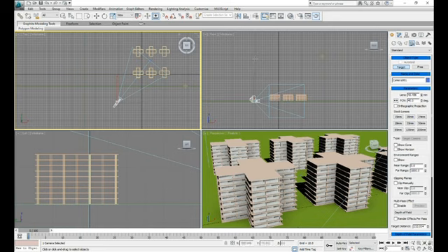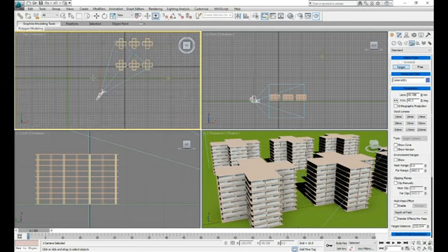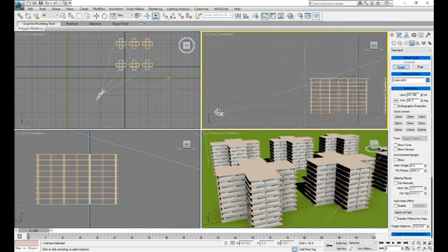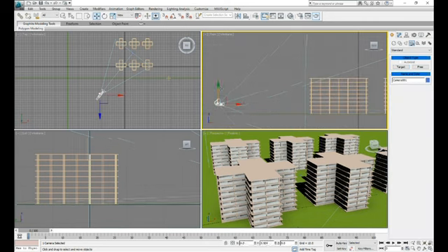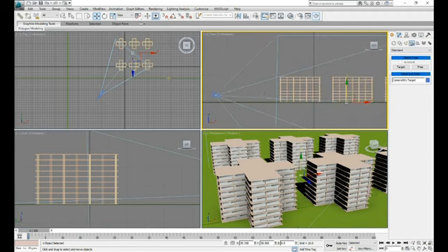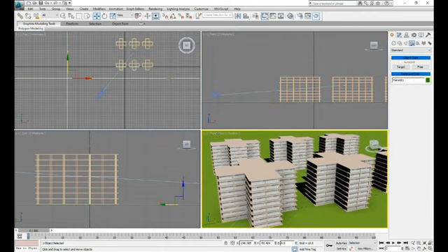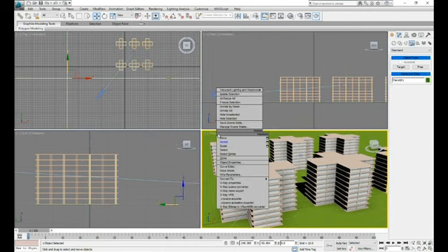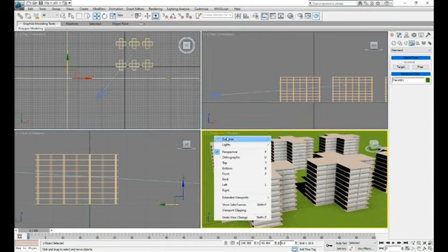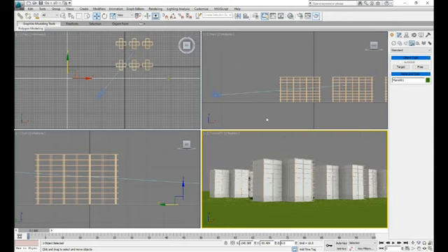So changing height is not possible in the top view. What we will do, we'll go to the front. Okay, let's say I will move this one. That will be my height. I will transfer to the camera target. It's here now. It will look like that. Check what happened. This is perspective. I will just right click. I will click camera 1. See, it changed instantly. Just as easy as that.